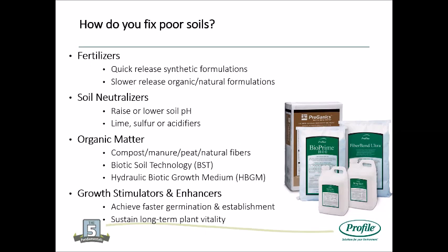Next, increasing organic matter on a lot of our construction soils is vital to the success of our sites. Some of the historically relevant organic matter additives are compost, manure, peat, a wide variety of things you can add in that sense. Also, just incorporating what we term topsoil. There are a lot of loose descriptions of topsoil out there, and really honing in to make sure your topsoil is actually productive topsoil is something you should be doing on a regular basis.